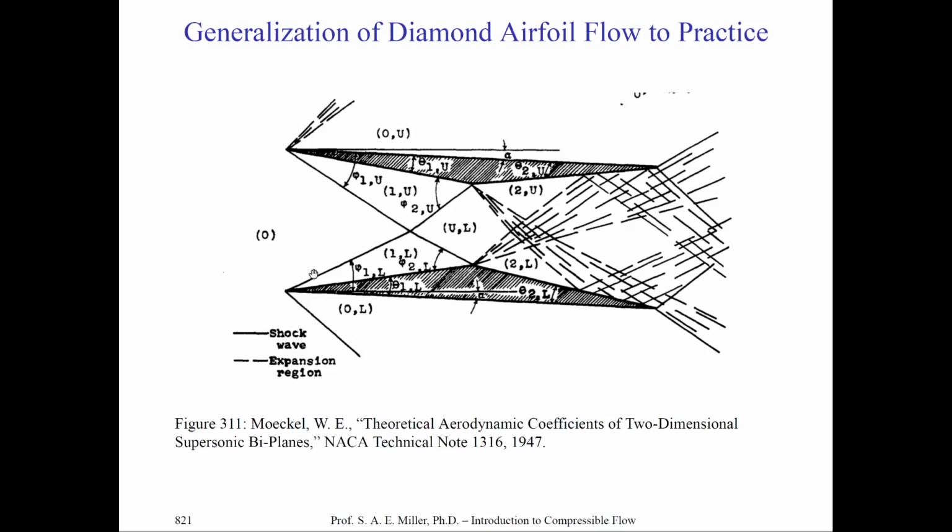In fact, shock waves form on the top and bottom of the vehicle triangular airfoil elements and merge into a reflected oblique shock. If we have an appropriate incoming Mach number and position these triangles exactly at the correct locations, these shock waves will reflect and exactly hit the tips of the triangles above. It's not required, it's just we have positioned the triangles and the angle of attack and Mach number to exactly get this case.